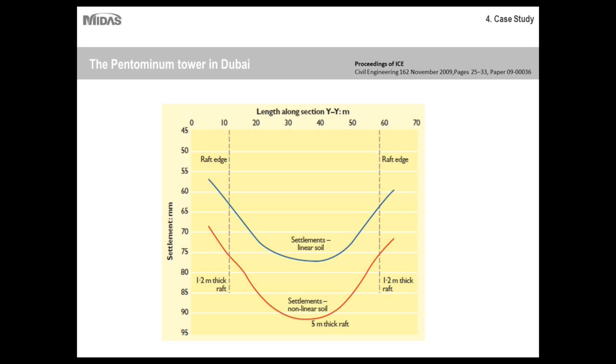A substantial amount of testing was carried out for the design of the Pentaminum Tower foundation, which included soil and rock testing as well as a comprehensive pile testing program, which the numerical modeling program was able to contribute to. In addition, complex geotechnical finite element analysis was carried out, which had been validated using standard geotechnical calculations. The application of such testing and analysis approaches has resulted in a very cost-effective and optimized foundation design solution.